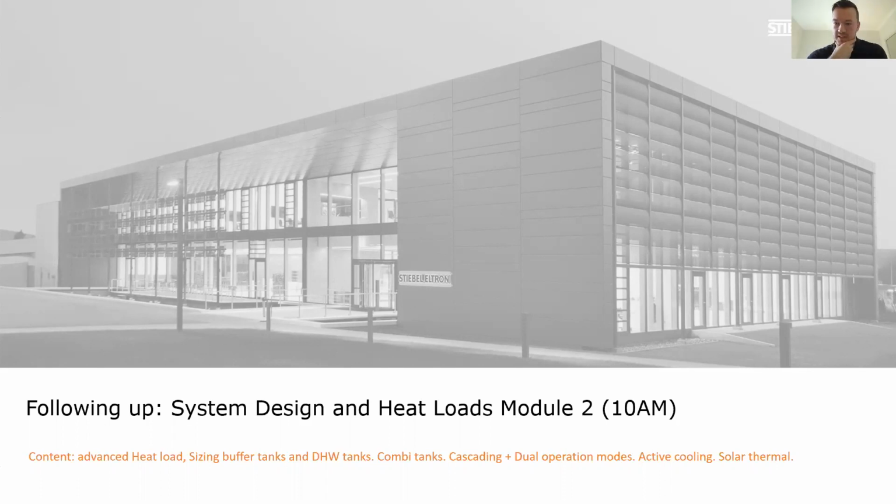All right, so the question is, do you factor in air tightness when estimating heating and cooling loads, or just assume 15 square meters or cubic meters for a very leaky building? We would factor it in. Again, it's something for module 2 maybe, but with the rule of thumb approach, we would probably not factor in air tightness. We just look at, as I said, a couple of variables and say, look, this is going to be 70, 80, 90, 100 watts per square meter, and the same for cooling.